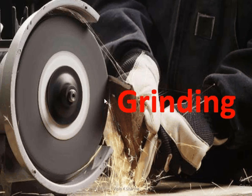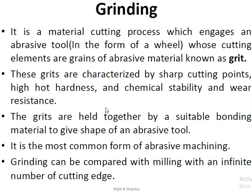This grinding wheel consists of several elements, and out of those elements, the important element is the grit or abrasive. So this grinding wheel mainly consists of number of grits which are bonded together with the help of some bonding agent in the form of a wheel. So when the sharp grits makes a contact with the workpiece surface, those grits acts as the cutting tool and removes the material